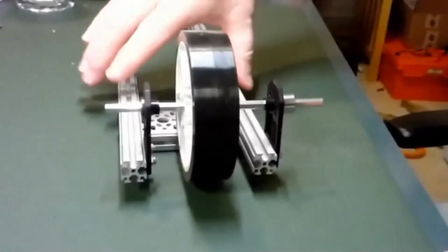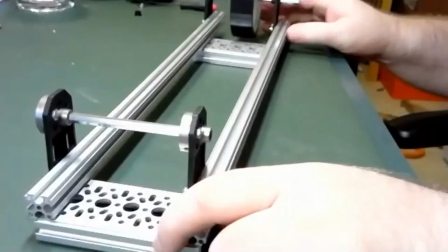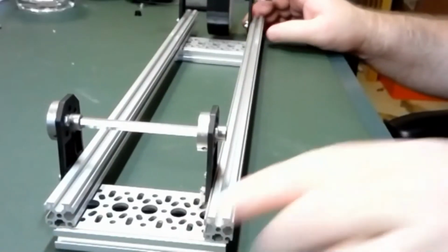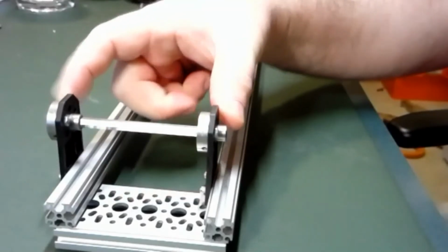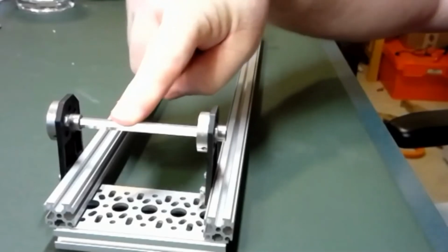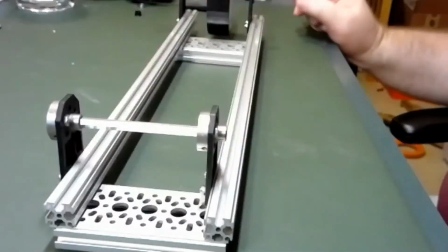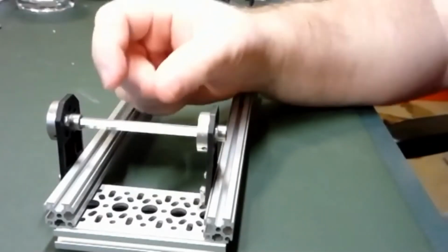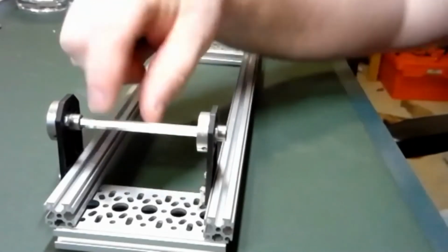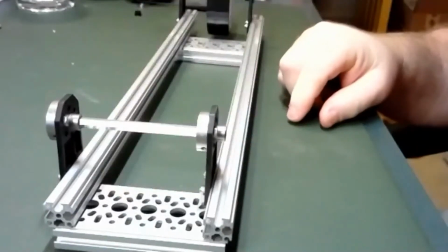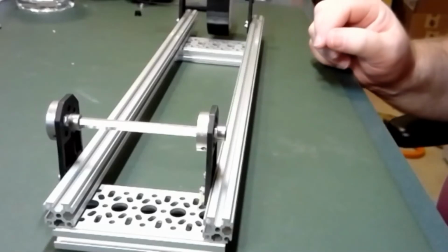With a dead axle, and I'll just flip this around, you still have an axle connecting the items together, but instead of the axle spinning with bearings in the mounts, the axle is fixed and the wheel turns around the axle. So that's a dead axle. You can do that fairly easily. It just means your motion bearings are on your wheel assembly instead of being attached to the axle. And by using a dead axle, it changes the strength of this structure amazingly well.